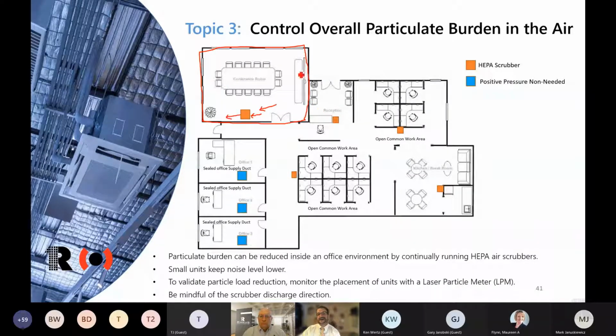So areas like a lounge or something like that have to be considered differently. But if you had an office environment in the school where the office did have one supply duct coming in and one door, well, this becomes positively pressurized, this office. And so if there are good filters inside the mechanical system, the positive pressure is constantly moving air out these doors. So this is a much safer environment. Plus, usually these single offices, the risk is much lower because there's only one or two people inside the office to begin with. And then again, we have respirators.